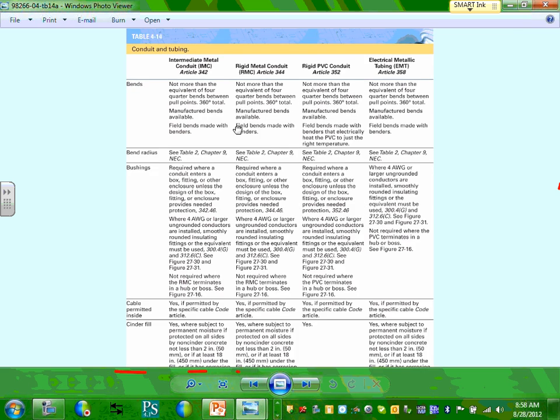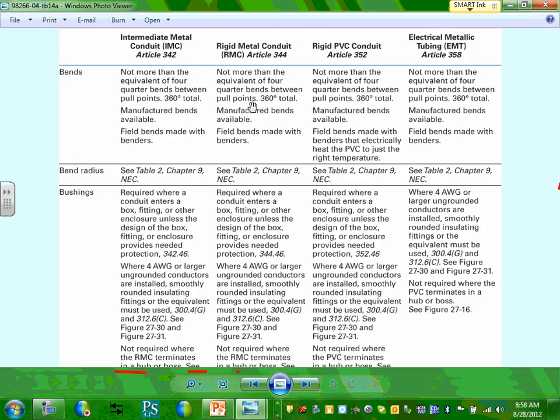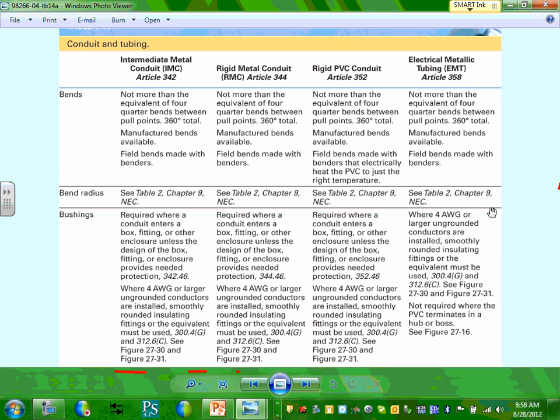All right, the next table, guys, is summarizing the conduits. We talked about conduits. Look how many conduits. We have 3 metallic conduits and 1 non-metallic conduit. All of them are non-flexible. So I have the rigid, intermediate, rigid, and PVC and EMT. Between EMT and MC cable, you will cover 90% of your commercial wiring. Cool. In residential, doesn't mean a whole lot.